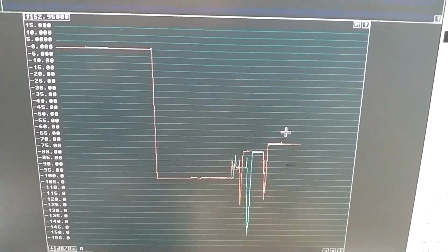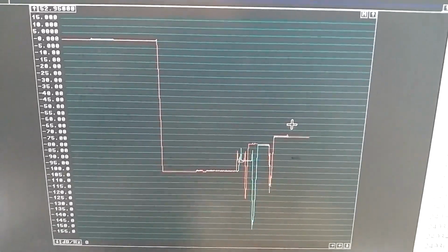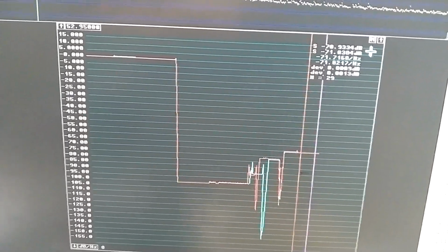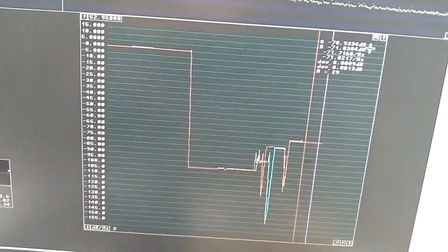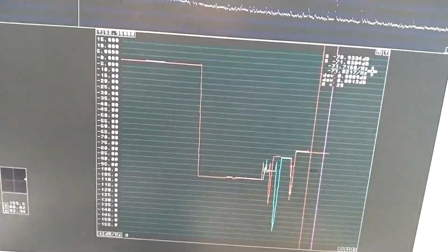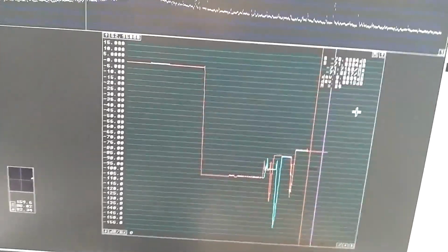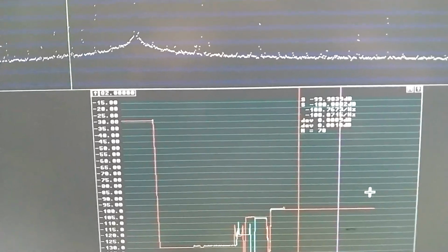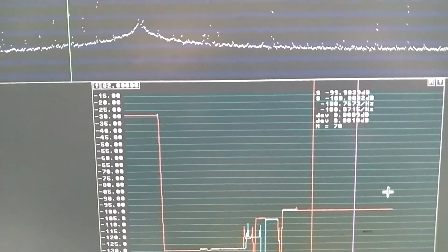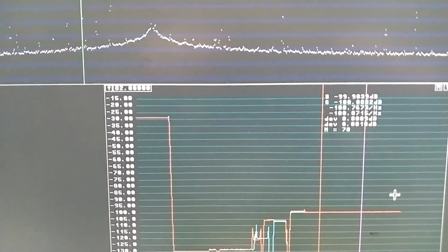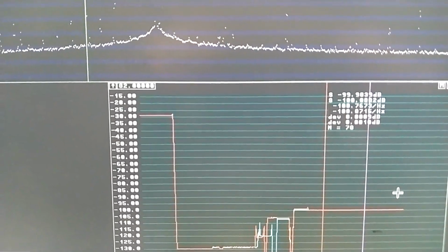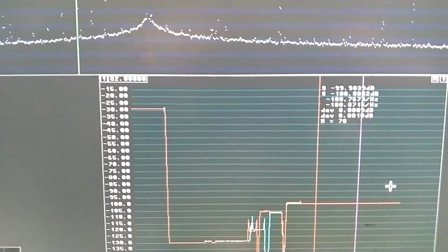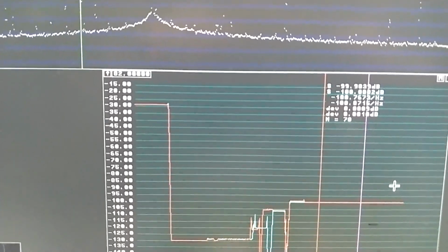I have increased the sensitivity of my two-channel receiver by about 29 decibels, it seems. But the signal is the same. It is 100 decibels below the oscillator carrier level. So I will recalibrate for this signal to show minus 100. Now the S-meter graph shows minus 100 for the generator signal, which I know is 100 decibels below the carrier from the oscillator when it is running in normal oscillation mode.